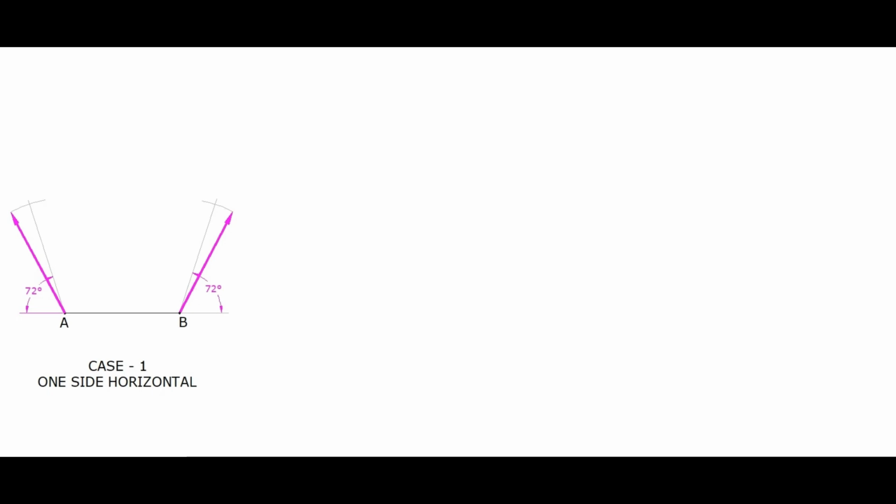The point marked on the line drawn from B is C and the point marked on the line drawn from A is E. Again with the same radius, cut arcs from both C and E. These arcs intersect at D. Join C and D and E. Thus the pentagon is constructed.